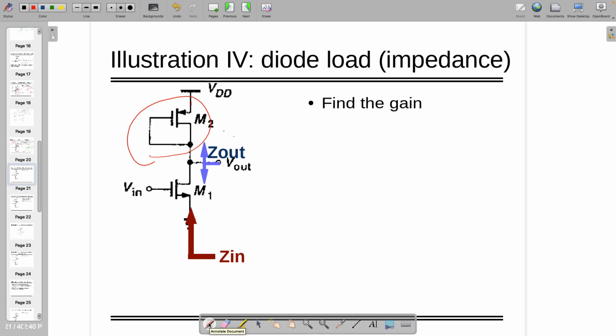What will be the gain? Let's write it down. Gain without channel length modulation. Without channel length modulation, what is the gain? Minus gm1. Let them answer. You have already studied even higher courses, right? Minus gm1 by gm2. So this is the answer for this one, right?